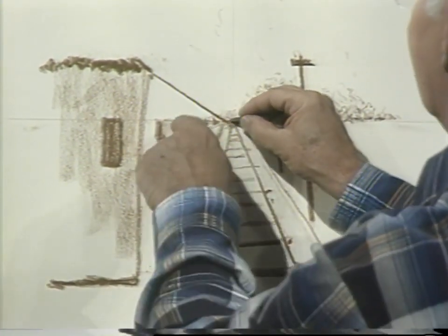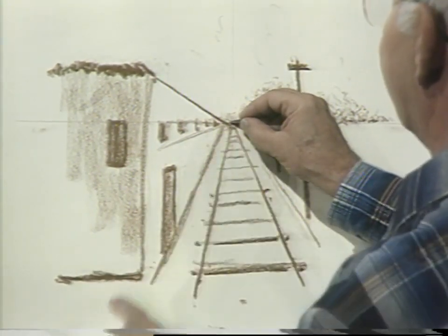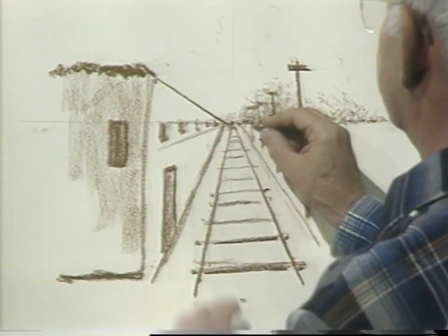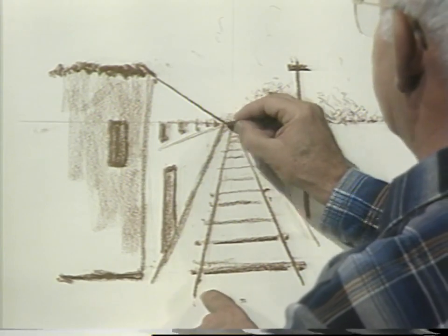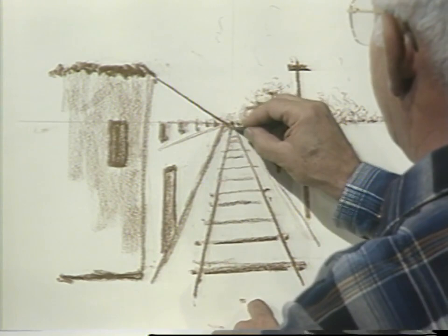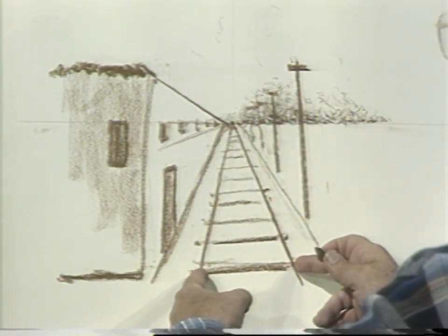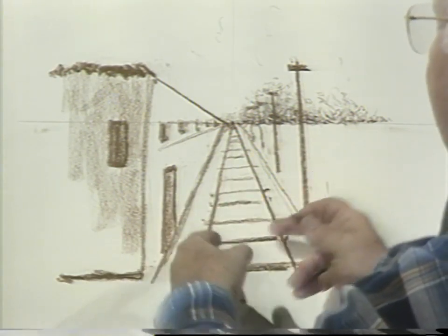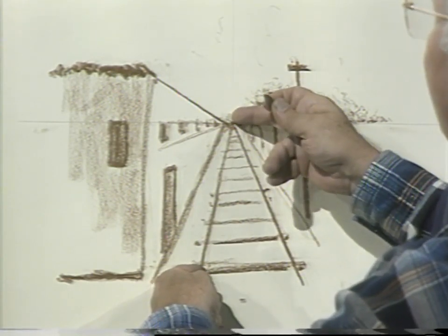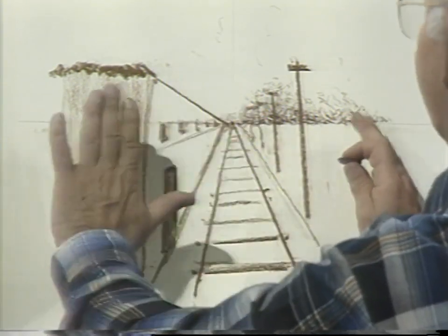Now I know the level of my eye and the point on the eye level which all lines will be drawn from. All lateral lines will recede to this point. And you see the side of the building went that way. You see the railroad tracks come to that point. I determine how wide I want this, or how wide I want anything on here. But once I determine that, then we have one point to go to in a one-point perspective. And all these lateral lines will go down to that point, not the front lines.